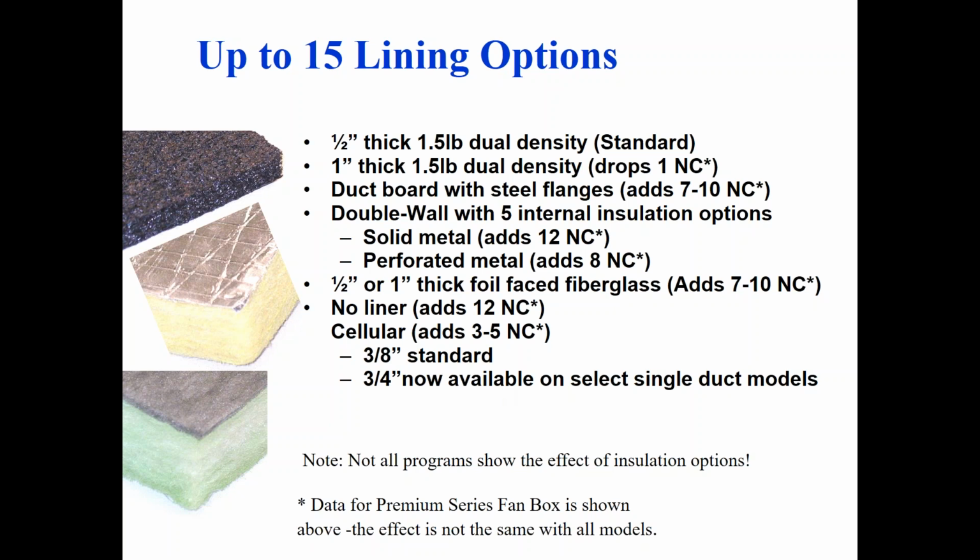It's kind of impressive. So on a normal job, I'd say stick with the 1/2 inch fiberglass liner. And if you have the need for washdown ability, which is not common, but if you did, get the cellular liner and forget about everything in the middle. All it's going to do is cause you more sound penalty than you want. The cellular liner is going to be the quietest of the washable liner options.